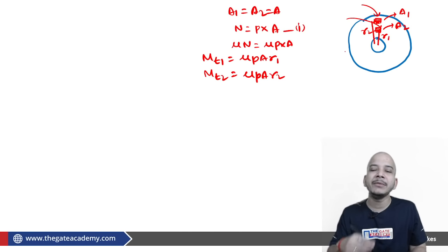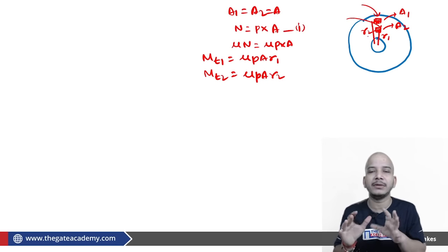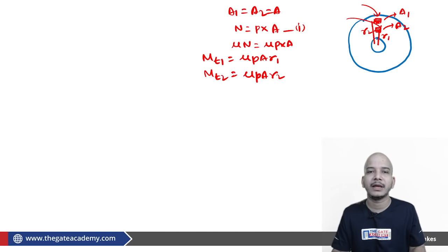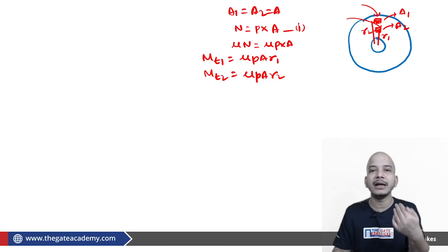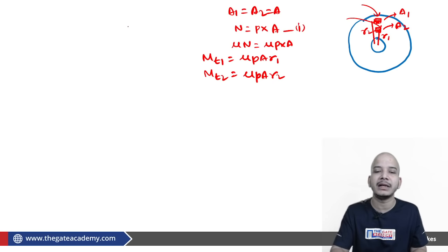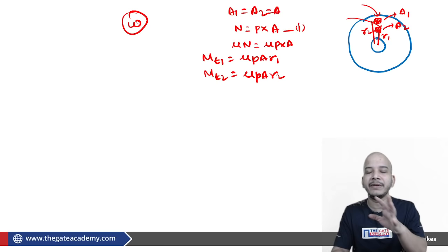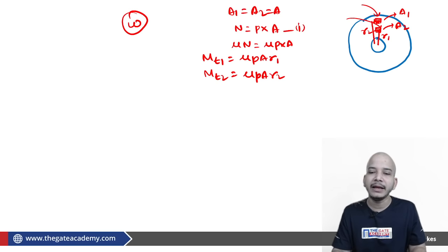Now if I am talking about a situation where there is a relative slip, because unless there is relative slip, this point cannot be made. Say the relative angular velocity between the driving and the driven plate is omega. Then the work done by friction per unit time means friction torque into omega.